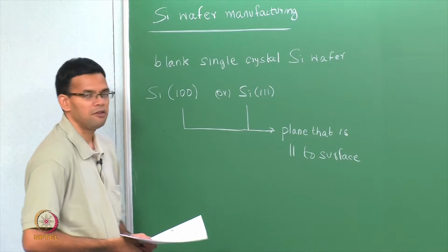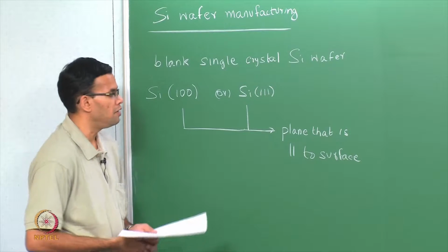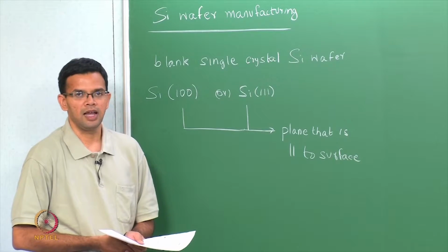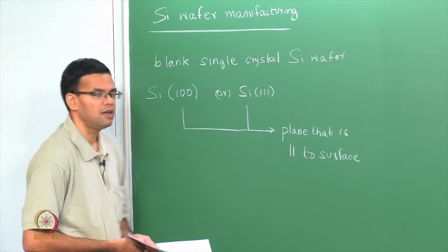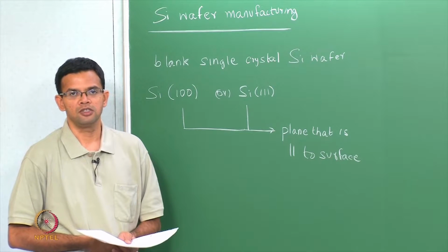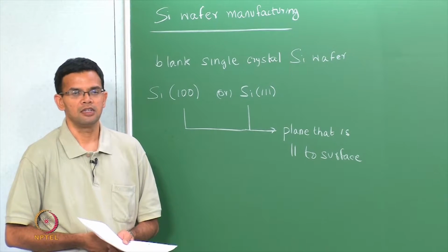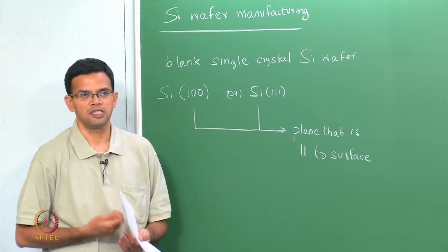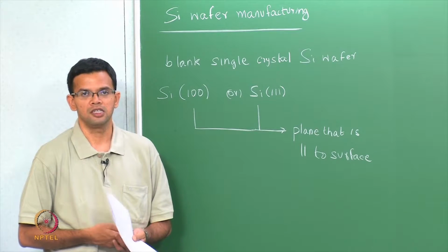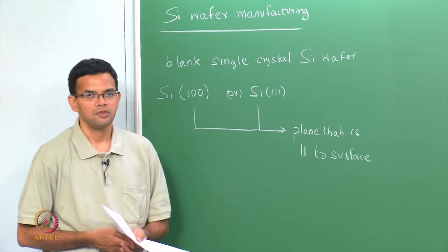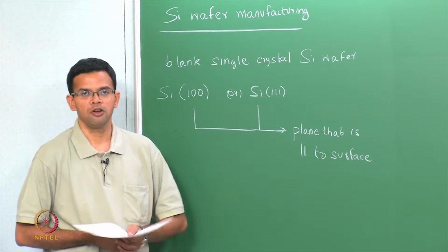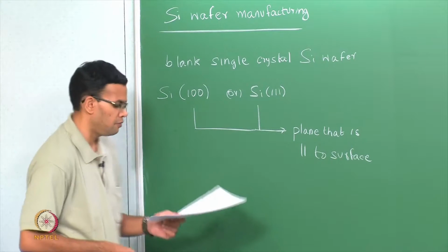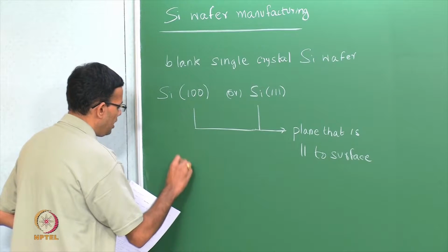We also need to manufacture these wafers with very low defects, for example things like dislocations, because these in turn can affect the electronic properties. More importantly, defects can also cause the device to fail, because later we will see that these wafers go through a whole bunch of processing operations, thermal gradients, stress gradients, so that defects in the crystal can cause the wafers to break. They must also have very low impurity concentration, especially metallic impurities should have concentration less than a few parts per billion.